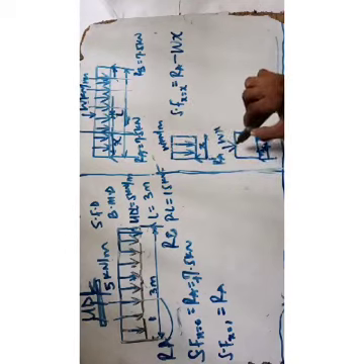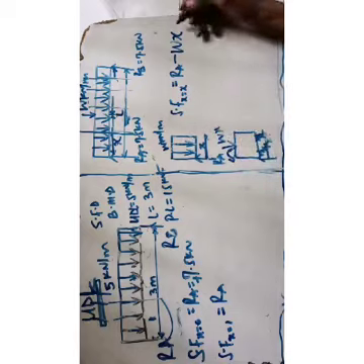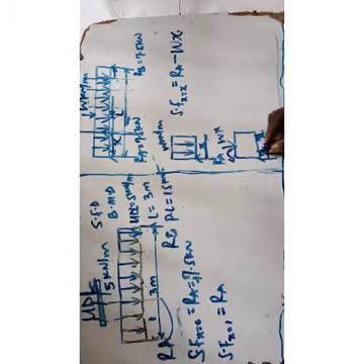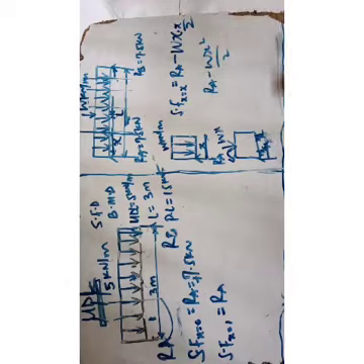It will convert to point load. Then you now take the normal shear force. That is, you now multiply. That will be W times X. You know, this is X over 2 times X over 2. That will now be RA minus WX square over 2. That is the shear force. So you can take this shear force for every point.